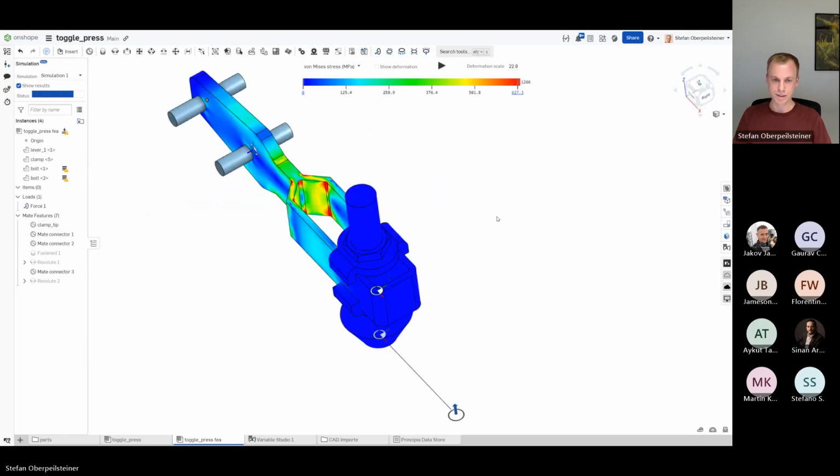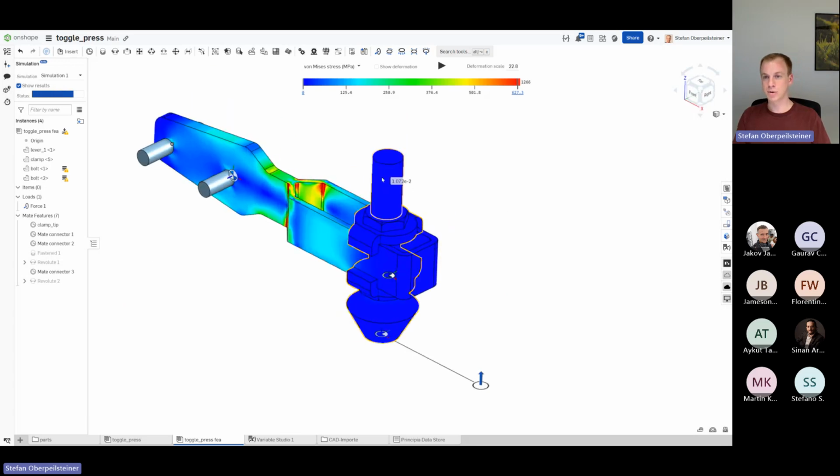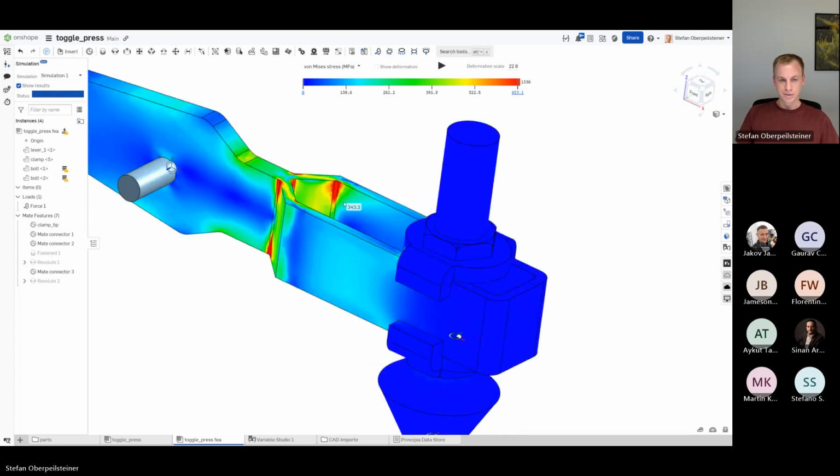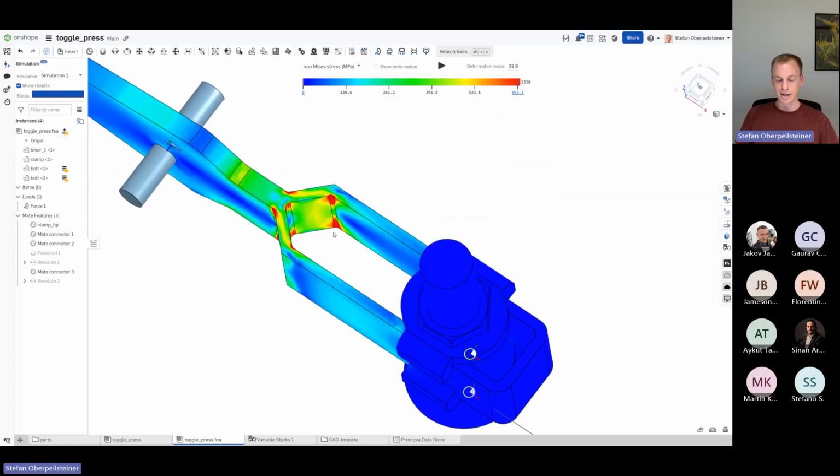So once the simulation is done, I can, of course, post-process something. I see this force obviously is too high for my part, but I exactly took the peak, which is only acting in a very short period of time. And here one has to say that these very fast deformations are probably not the real thing for this static finite element analysis. But anyway,